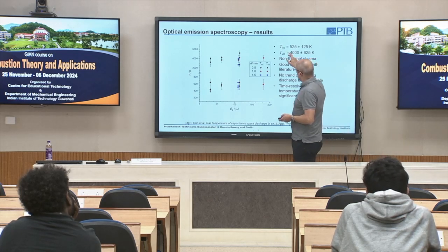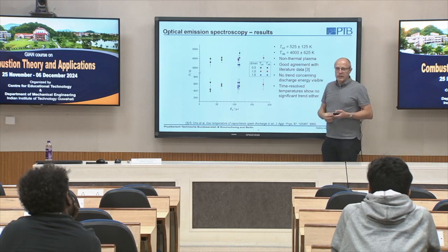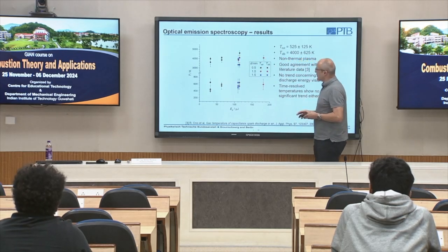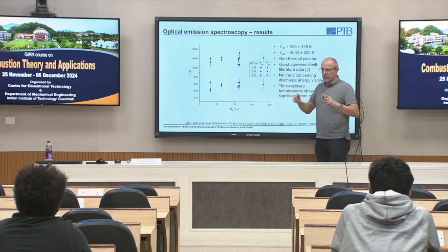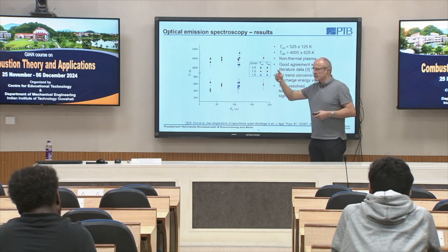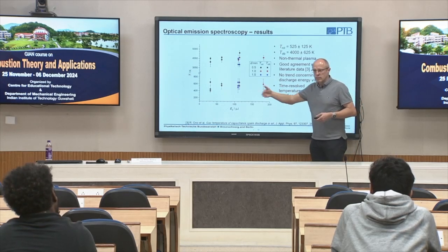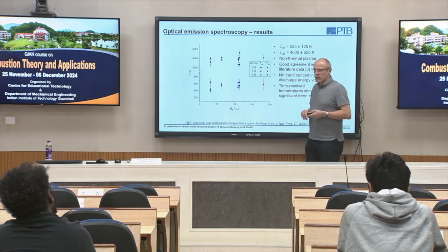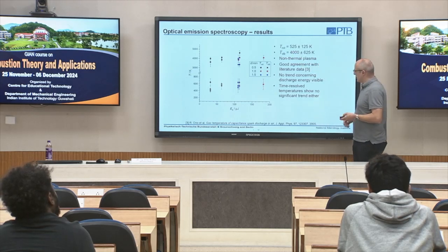So what is the main influence of this part here? A lot of energy is deposited into the vibrationally excited nitrogen, and this is something like an energy storage. This nitrogen then collides with other molecules, and the energy is transferred to the other molecules, leading to higher translational velocities, leading to higher temperatures. So we just store the energy here, and finally we need it, of course, for our combustion process.